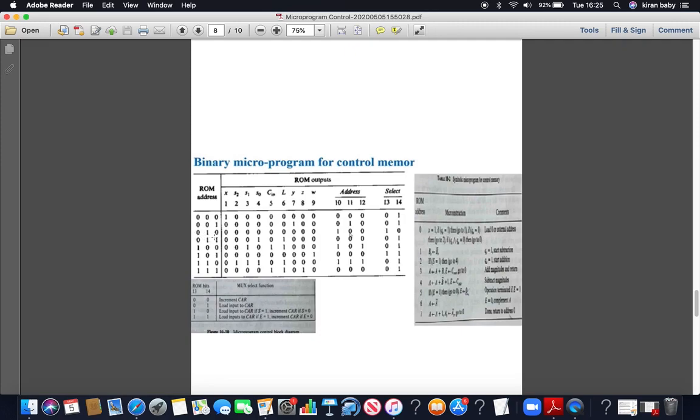Okay, inside 010, we are performing a comparison operation. We are just checking the value of the sign bit. If S is equal to 1, that is, we are performing the XOR of the sign bits. If S is equal to 1, then you are going to step number 4, that is, you are going to perform a subtraction. If S is equal to 0, we are going to perform an addition operation. So in this case, that comparison doesn't require any registers to be set. It is just a comparison operation. So none of these bits are being set here, and the address that needs to be loaded is 100, and the selection line is 10.